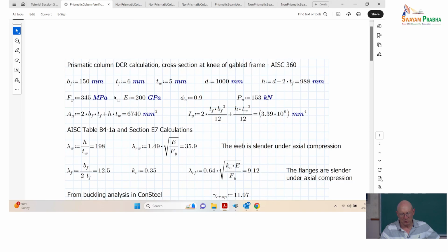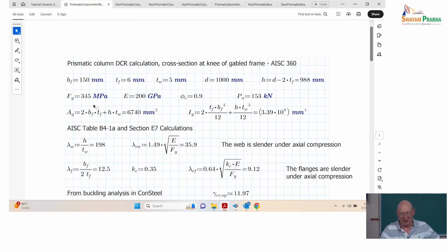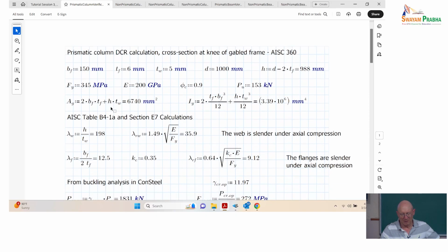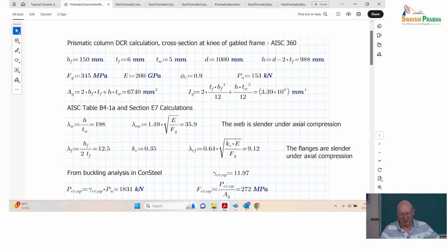So you're using grade 345 steel here. A lot of metal buildings manufacturers in the U.S. often use what we call grade 50 steel, 50 ksi yield, and it's very common to use a grade 55 steel in the U.S. Would that be common also in India?